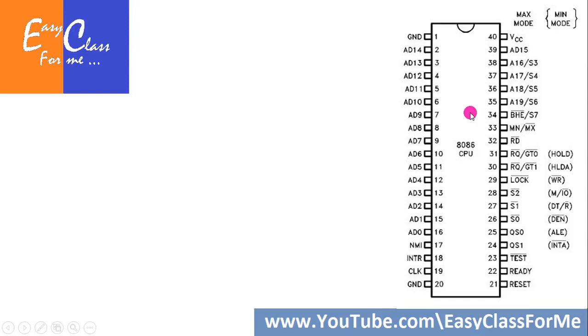Whenever an address is given on these address buses, AD0 to AD19, a total of 20 pins, that address has to be stored somewhere for future use, because in the next timing cycle this address and data bus will be used as data bus only. To enable that, we have address latch enable.